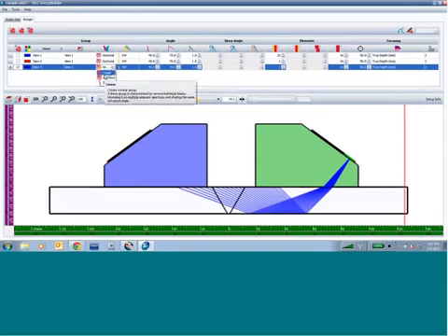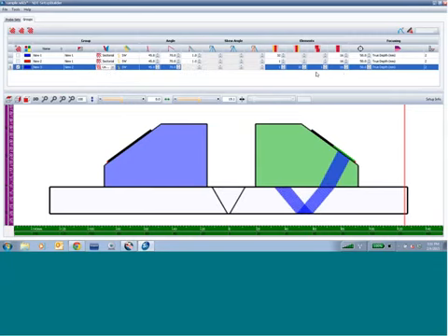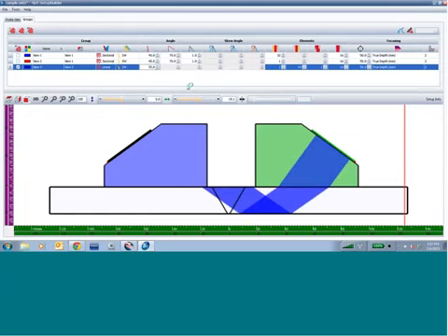So if I wanted to try and carry this out with linear scans, I really have to pay attention to where these beams go and make sure that I'm actually getting the right amount of coverage. Again, if I start with the bevel, I have to be careful with how close I put the transducer.